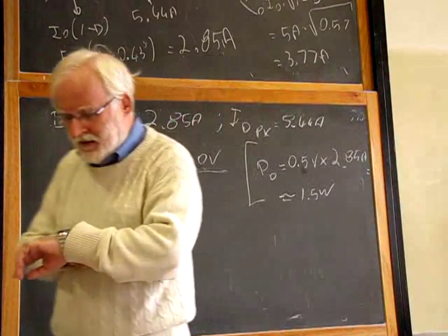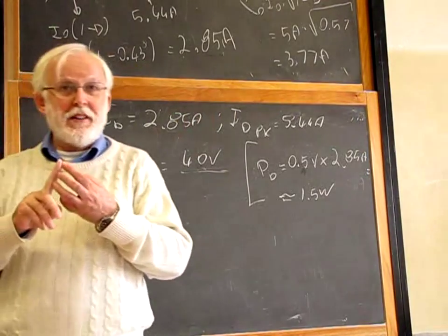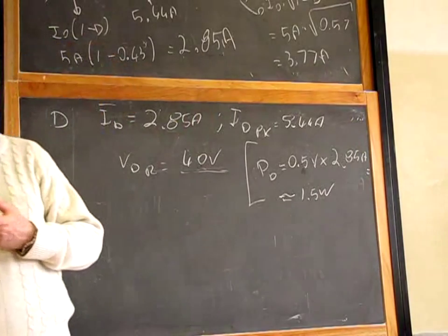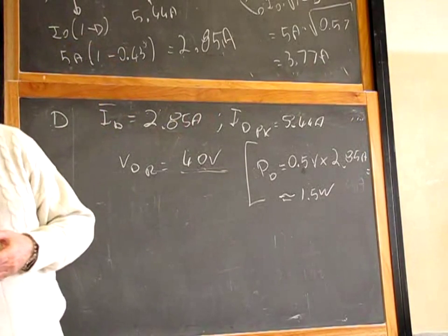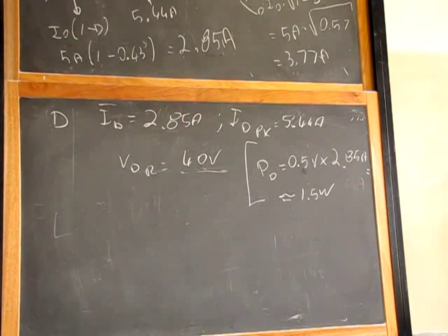Okay. Our diode is done. Three numbers for that: average current, peak current, and reverse voltage. If it is a Schottky diode, or a silicon carbide Schottky diode, your diode is intrinsically very fast. There are no minority carriers. If you choose a standard PN diode, for example because your reverse voltage is 200 volts, you need a standard diode. You can't use a Schottky diode.